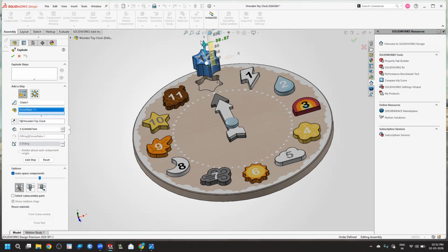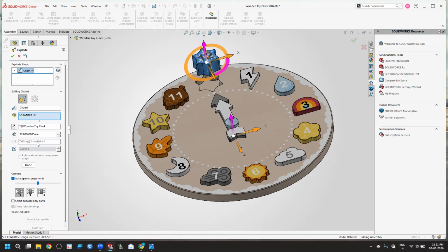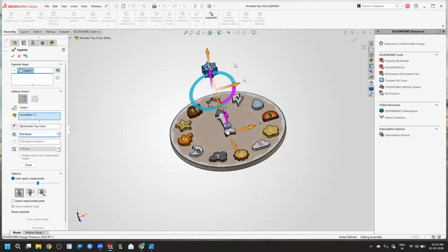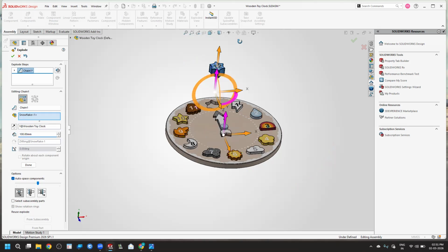If you can't place it right using the scale, you can make use of the distance box in the exploded section, where you can put whichever dimension you want. Here I'm putting 100 mm. You can see the object is placed at a 100 mm height in the Y direction.